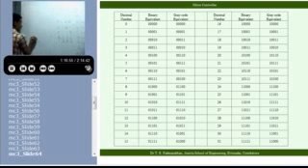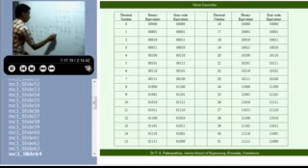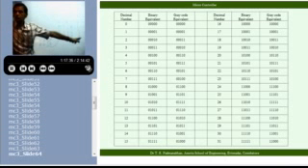Suppose it is changing from 0, 1, 1, 0, and then it goes to 0, 1, 0, 0, then to 0, 0, 0, 0, then to 1, 0, 0. Suppose the change sequence is like this. During this time, if by mistake you are slightly off at the time of reading, it will be interpreted as either a 4 or a 0 or an 8. So you can be very much in error. This type of error will not creep up when you use a gray code.